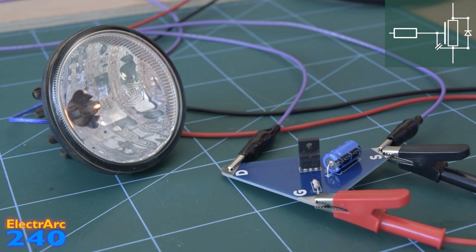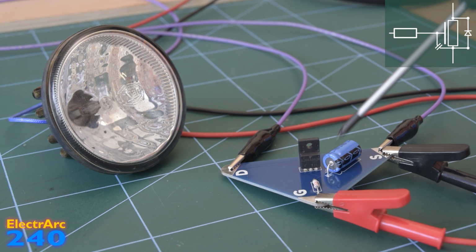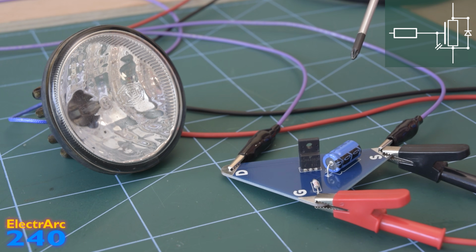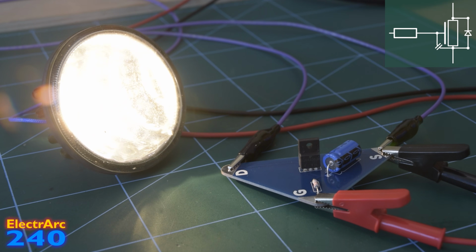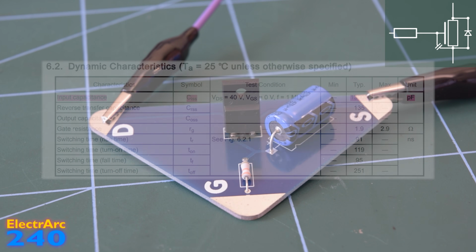and the same is true for turning off. This is because our gate resistance limits the current we can put in and take out of this capacitor. And because we are switching off and on slower now, we are spending more time in this lossy region with the channel resistance soaking up quite a lot of power. This will cause the MOSFET to get hot, and is quite often a source of more loss than the conduction loss. If this loss isn't accounted for, with cooling on the MOSFET, it's going to ultimately result in release of the magic smoke.